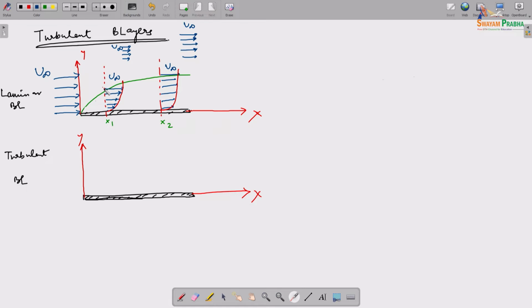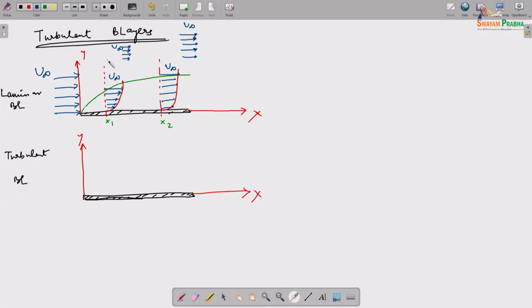this green line is not a solid or real boundary in the physical flow. This is only for our illustration here. You keep moving away in the y direction, and we reach a height where it is just about u infinity. The typical description is 99% or whatever, which is up to you, where you essentially get back the free stream.